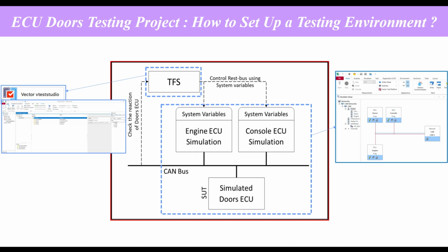Both ECU simulations are controlled using system variables. As you see here, the engine ECU and console ECU are controlled using system variables, which allows us to manage the rest bus simulation and dynamically control the test scenarios. We will see this in detail in our next videos.